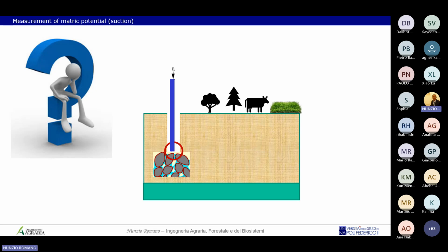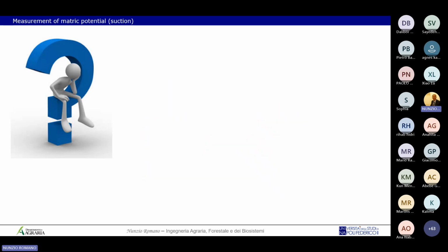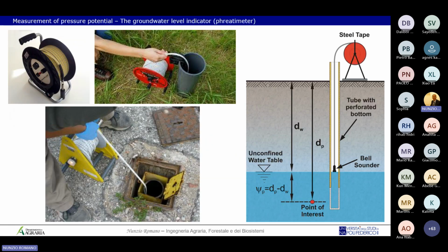No, the aquifer is just below, where the soil is just up over the water table. So we are not dealing with the aquifer. But you can see here for the aquifer you have the piezometer. Again, if I was not clear, the piezometer is a cylinder, a PVC cylinder or metallic, steel cylinder.